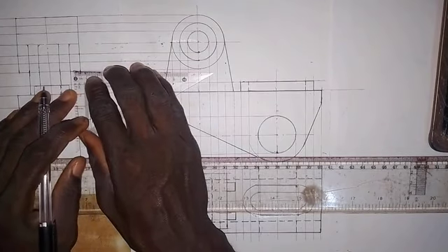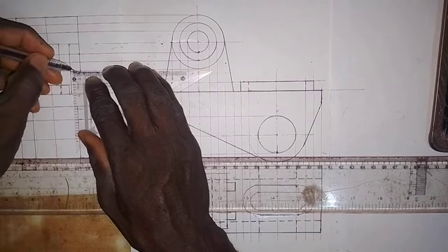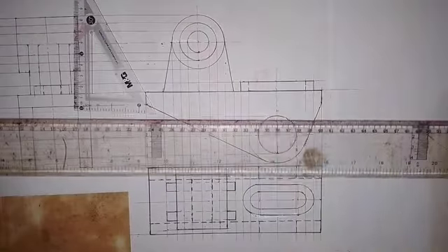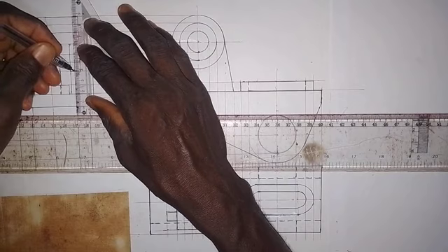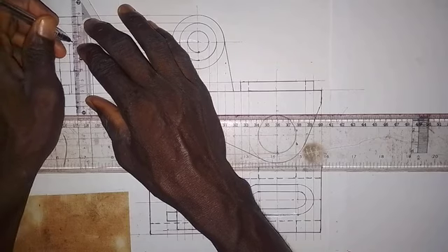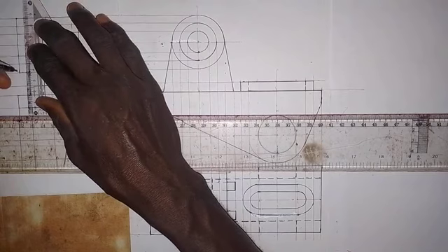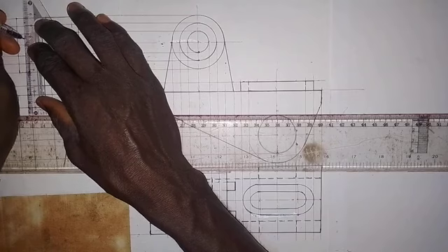it is 6 millimeters deeper than the big one. So we take 6 millimeters here, we also take 6 millimeters here, and the end of that hole we make a short dashes line, so it goes up like this. We also do the same thing here, so it goes up like this. Draw a short dashes line like this. Okay, so we have this now.